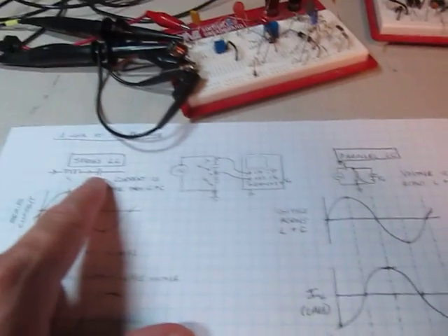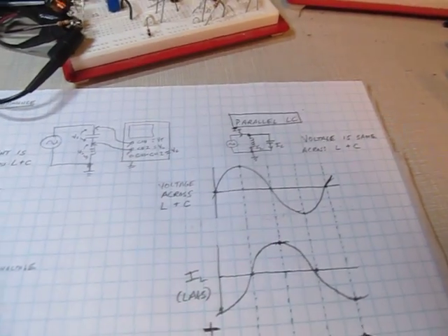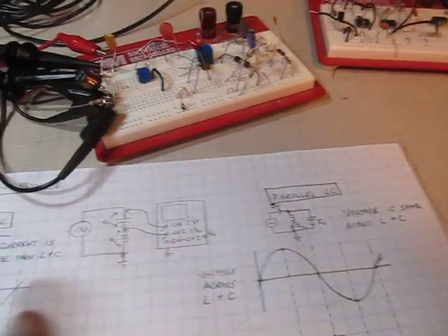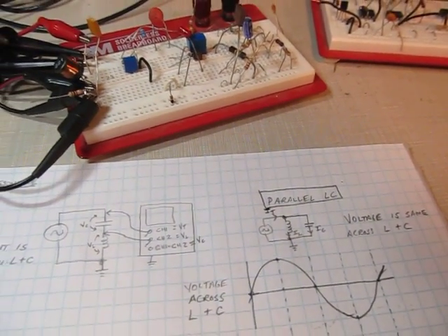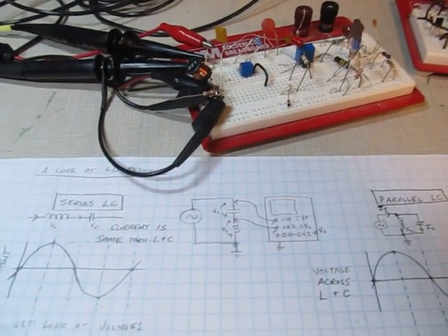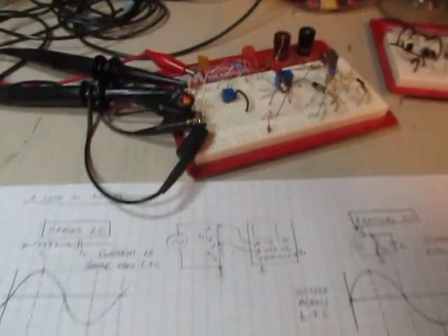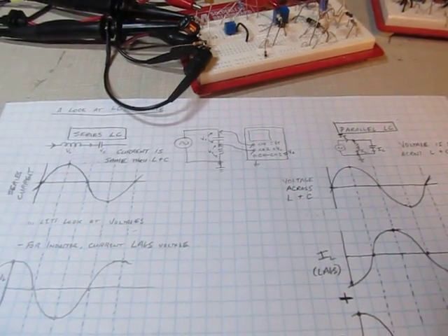So you can see some pretty powerful things that can happen here with series or parallel resonant circuits that allow you to create networks that will have either a short circuit or an open circuit at a particular frequency. And by playing with the values of L and C, you can create tuned circuits to create things like filters and other frequency selective networks. So it can really be handy in designing AC circuits. So I hope this was helpful in understanding what happens with LC circuits at resonance.